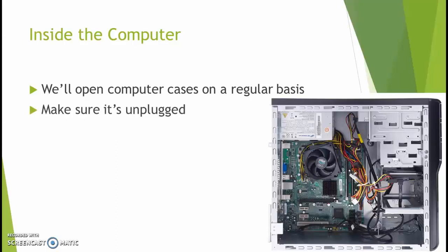When you do so, before you open the case, you should make sure that the computer is unplugged. And even after that, you need to show a bit of care. The metal edges inside the computer are not treated the same way as outside the computer, and they can be very sharp, and you can cut yourself pretty badly.